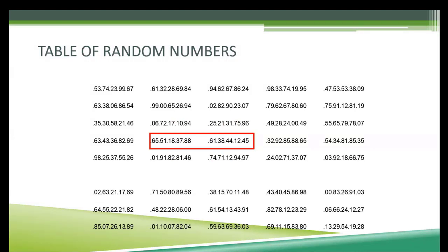Doesn't matter. You just go in independently in any place in this random number table. Start going left to right. Just stay consistent, or up and down. If you need one number, obviously your first one's 0.65, next one's 0.51. If you're looking at, say, cores behind the paver, you'd need two pairs of numbers.